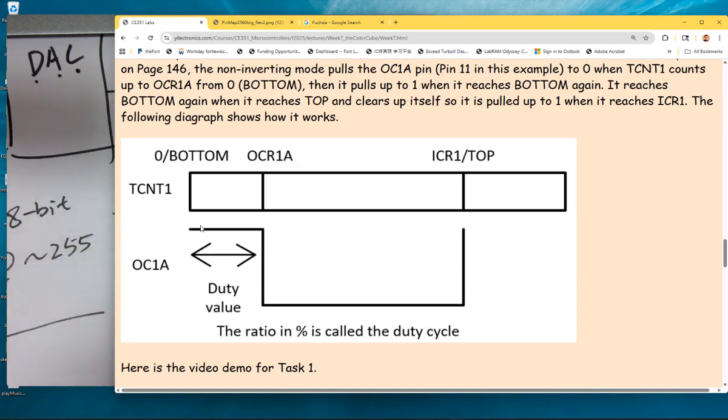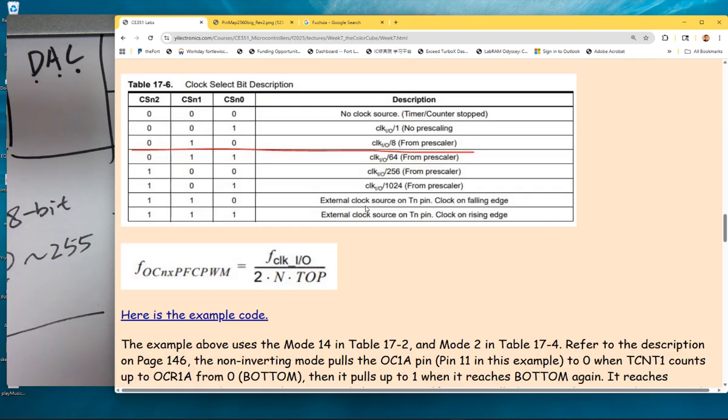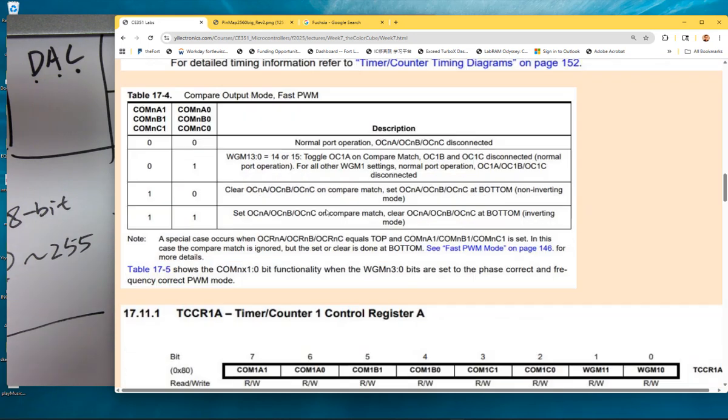Sometimes you may need it. So whenever this is getting, what is it called? It's an output compare register, right? So comparing with the counter's count. When the counter is counting, it's comparing with this value here. It's output compare A register. Whenever they match, it's going to pull it down by itself, and also a flag will be set, and I think that's TOV. Let's take a look.